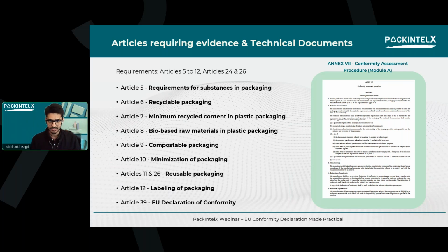But when we focus on polyolefins, especially food contact, big challenge, because today it's not allowed. So EFSA has not allowed post-consumer polyolefinic waste to go back into direct food contact applications. And there is a 10% recycled content requirement for such kind of packaging. Challenge. Another challenge would be: is there sufficient recycling capacity in Europe from where I can source the recycled materials?